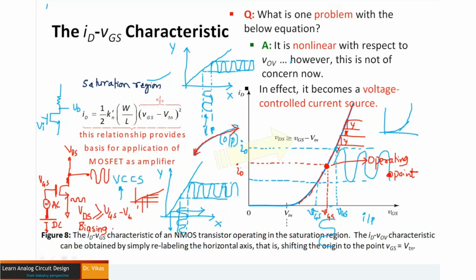That point can be identified through load line analysis or some other aspect, but in a simple way I can keep on differentiating this bigger curve into smaller chunks and find the slope, and the point at which I get the maximum slope, I can consider. If I give that much VGS, giving that value of I naught, here indicating ID, then I can say I can fruitfully make use of this MOSFET as an amplifier.